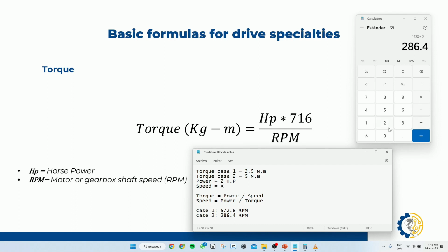At the moment when you already ran your auto tuning and you ran all of your possible changes, whether electrical or through our drives, or through our mechanical, maybe we missed grease or oil, and even so, it's not giving us enough torque, then in this case, it's time to call our motor reducer.